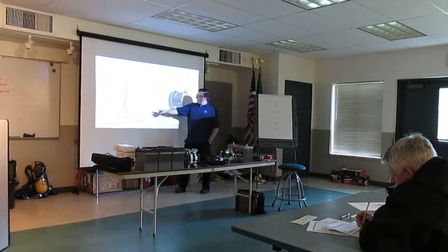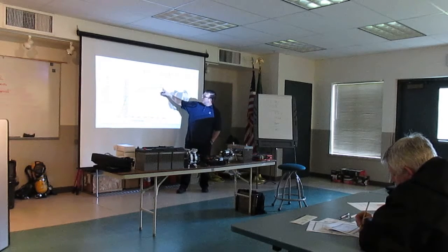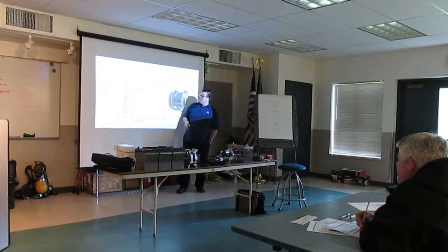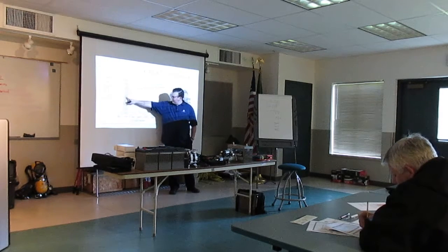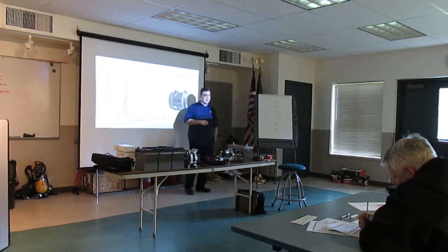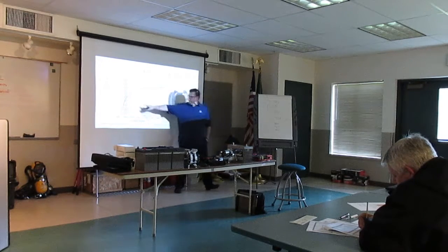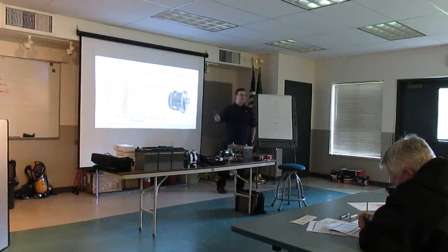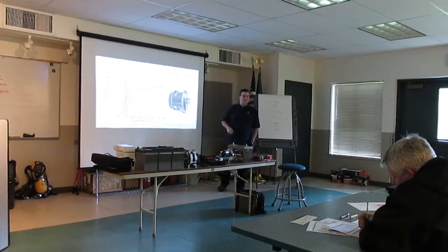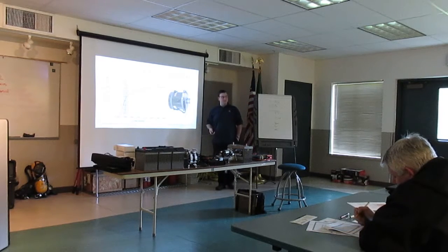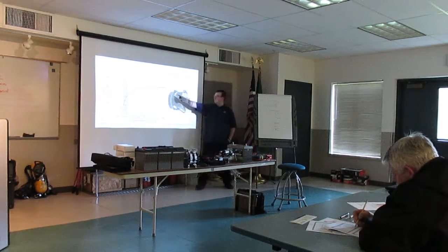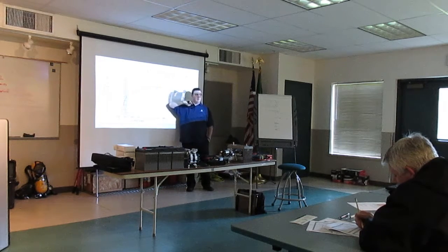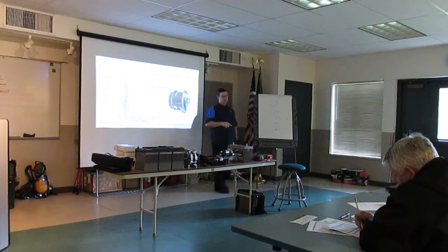So on the unit that is rated at 350, 375, at idle you're going to get 200 out of that unit. A little bit less once it gets hot. So even though you read an alternator and see that it says it's a 500 amp alternator, it is 500 amps at 6,000 RPM, because that's the point at which they take the rated output on the units.